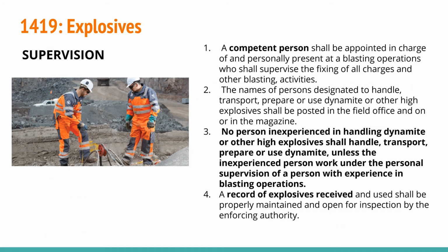Rule 1419 caters the ruling on explosives. The supervision of explosives is that only a competent person shall be appointed in charge of and personally present at blasting operations. The names of persons designated to handle, transport, prepare, or use dynamite or other high explosives shall be posted in the field office and/or in the magazine.